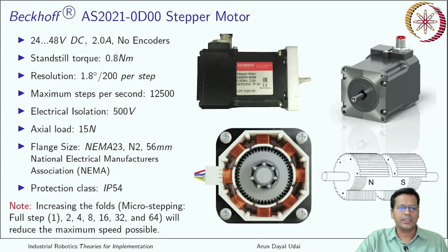Okay, so yes, this is the motor that I'll be controlling. You see it has a resolution of 1.8 degrees, pole to pole gap is 1.8 degrees. Mind it, this is not precisely a bipolar stepper motor. It is a kind of, because it has a dual property of a variable reluctance motor as well as a hybrid bipolar stepper motor, that is a permanent magnet motor.